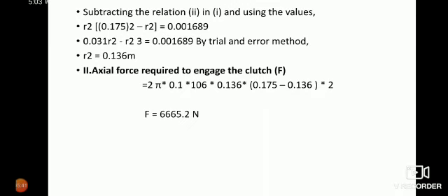Axial force required to engage the clutch, F equal to 2 pi into 0.1 into 10^6 into 0.136 into (0.175 minus 0.136) into 2. So the force F equal to 665.2 Newton.